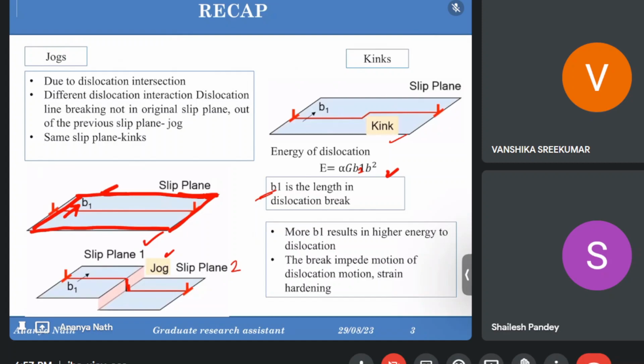Residual stress means we are applying some external force and having some percentage elongation, but due to strain hardening and other factors, we now have a strain hardened material whose ductility is not that much, but the stress has remained inside the lattice, which is called the residual stress.